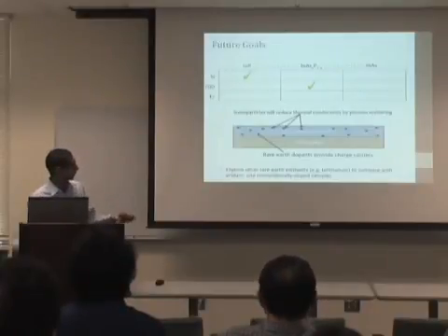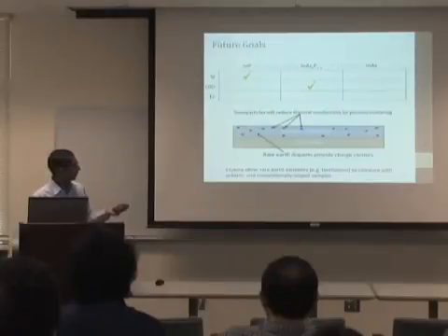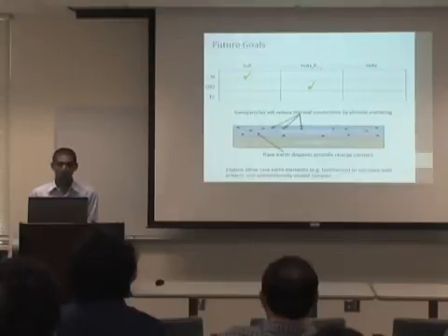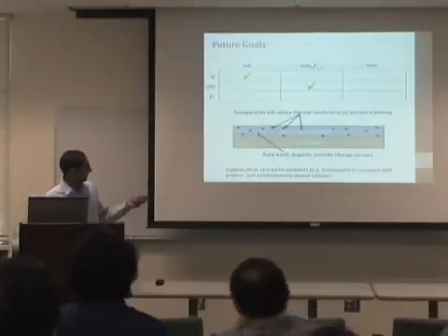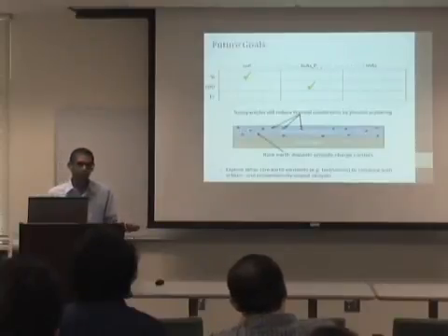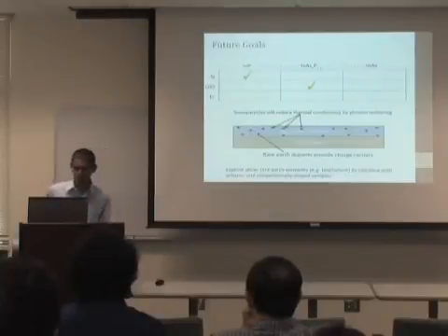And we're doping with rare earths because they have a chance of either incorporating into the material in low concentrations, and they'll provide charge carriers, or they can precipitate out of your material and give you nanoparticles, and those are another site for phonons to crash into, another wavelength of phonon you can scatter. You're really driving down that thermal conductivity. So once that happens, we can explore other rare earths to see if that actually makes a difference. So we might try a lanthanide, and we can compare it to our conventionally doped and unintentionally doped samples.